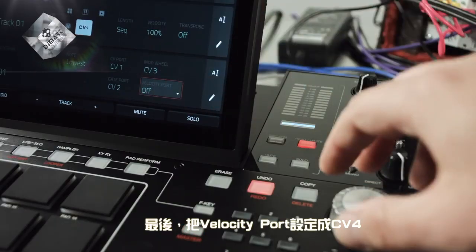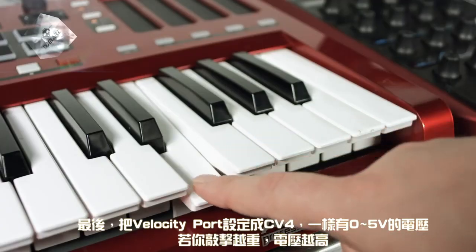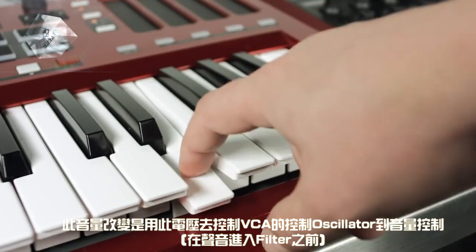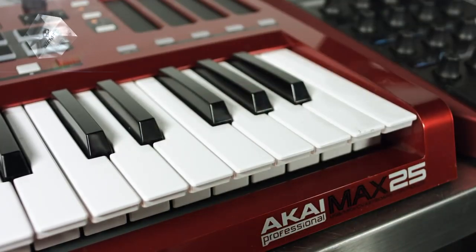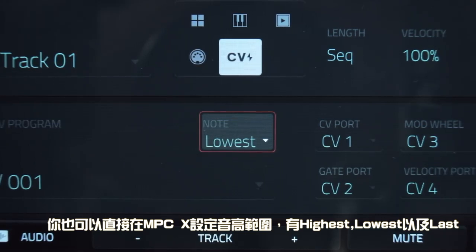Finally, velocity is assigned to port 4. This will give you a voltage between 0 and 5 volts depending on how hard you strike the pad or keys. I'm using this voltage with a VCA to control the volume of the oscillator before it gets to the filter. You can define your note priority behavior here as well.